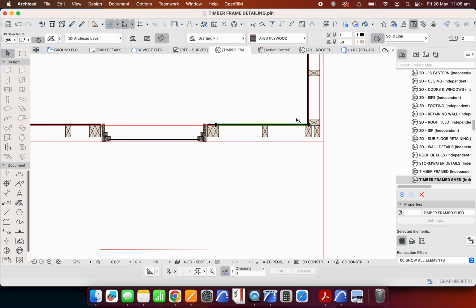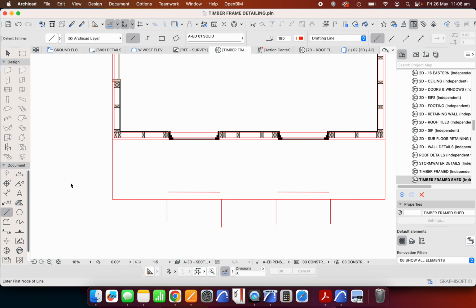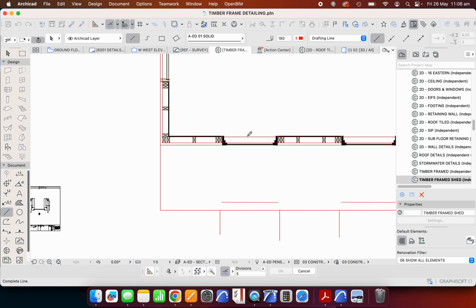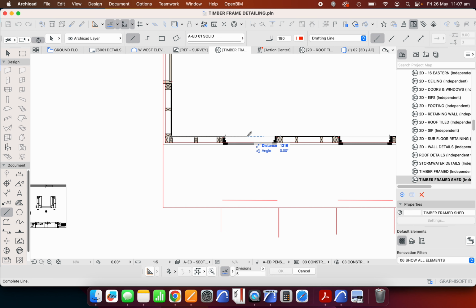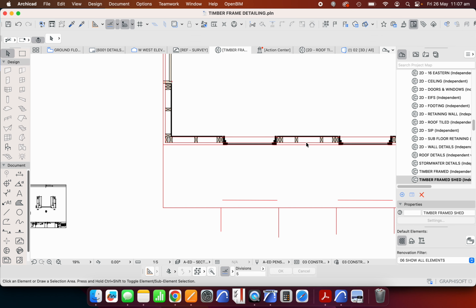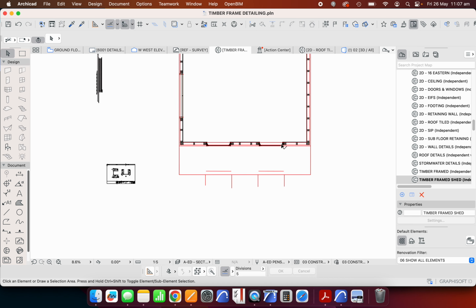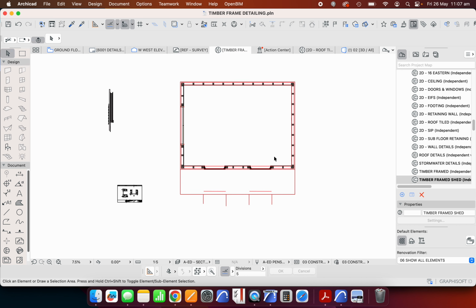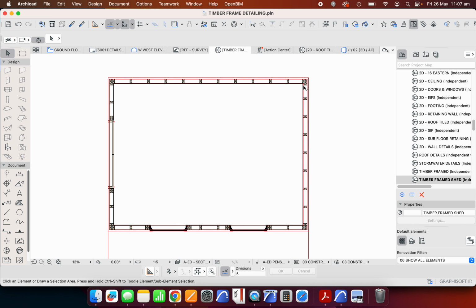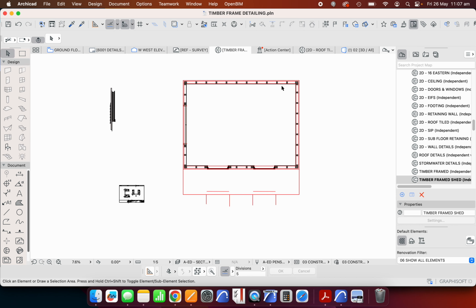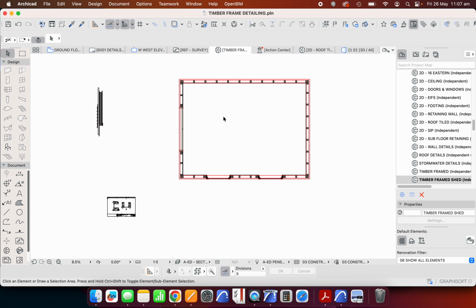Now, if I wanted to adjust this at all, I'd be saying, well, could I get away with having a full 1200 sheet of ply? We'd see that if I move that to be a full 1200 sheet of ply, these windows would end up bashing against each other in the middle. And so it wouldn't give us a very desirable outcome anyway. So unfortunately, there is a bit of wastage, but that's about as good as we can do. And of course, we were trying to be as consistent as we could possibly in the other walls where we're not creating wastage. I can delete all these extra lines now that we've done that. And our plan is taking shape.